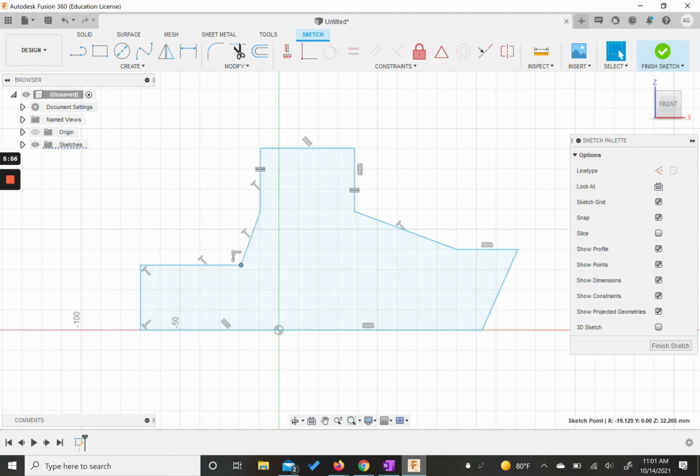All right, and then it says we have lines 3 and 9 align horizontally. So these two need to align horizontally. So what we can do is choose our horizontal vertical constraint and choose point, we have an error. Well, we'll do collinear instead. So collinear, we'll just do the actual lines versus the points. We can do those two lines. If you notice this one's really tiny now, we can grab our dot and move things around.